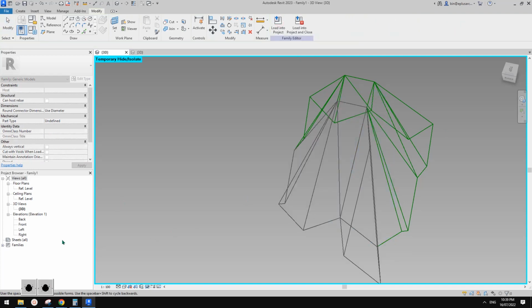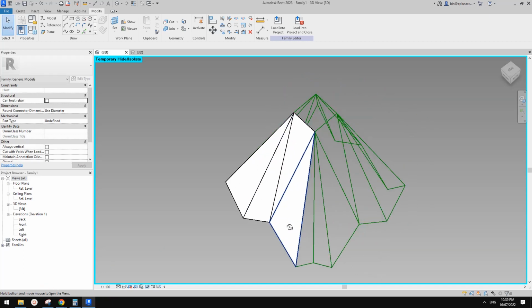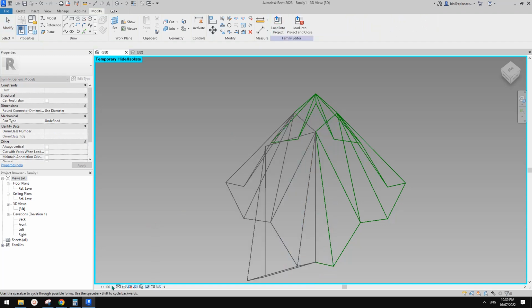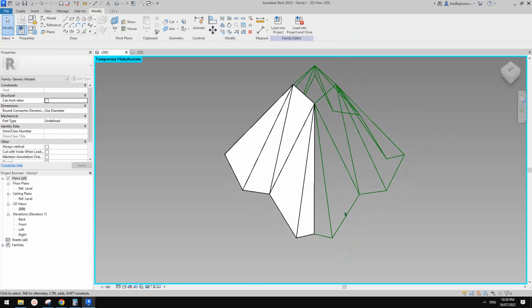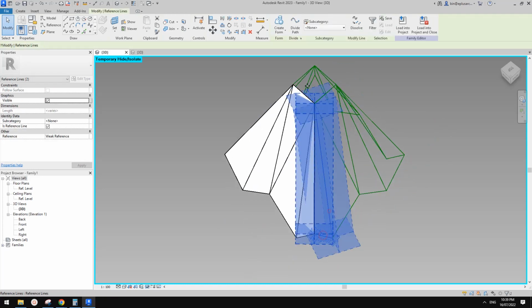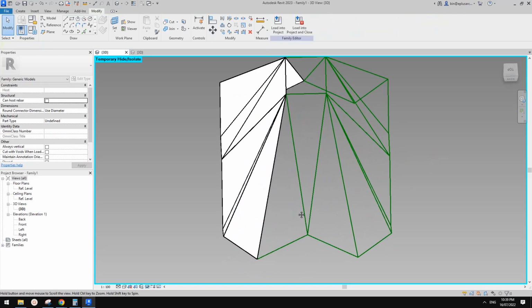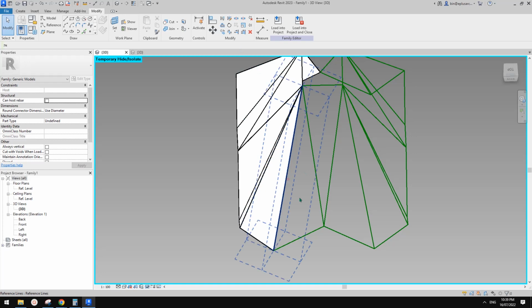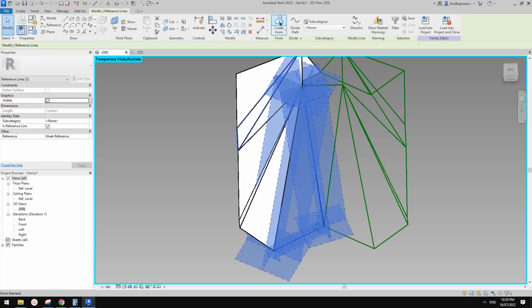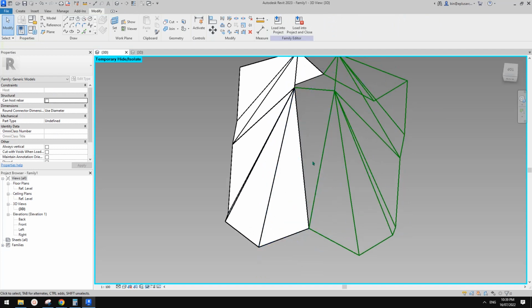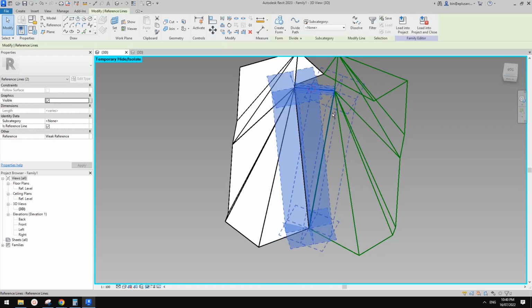Oh, here, options here. We can directly pick the one on the left, which is the surface. It disappears again, so just click anywhere to create a solid. Create a solid, and you don't need to go back to pick the face. You can just directly click on delete, and we'll delete that top surface.